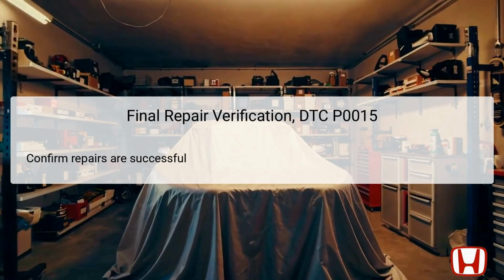Utilize Honda's diagnostic tool to clear the DTC from the PCM and monitor for the reoccurrence of the code. If the DTC returns, further investigation may be necessary, possibly indicating additional underlying issues that were not initially identified. Successful resolution will lead to a stable engine performance aligning with the expected parameters.